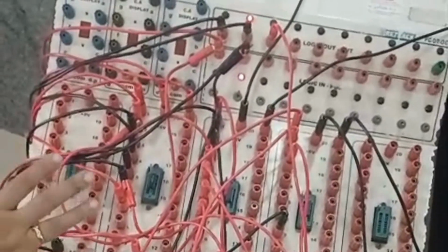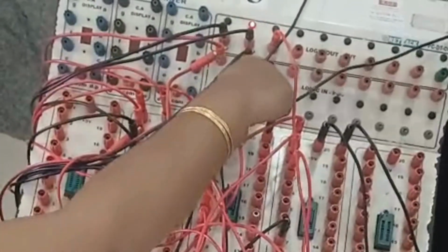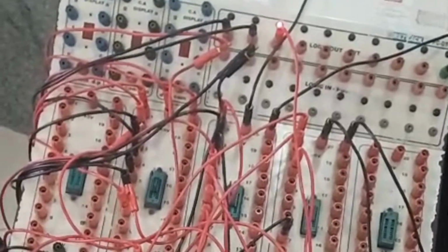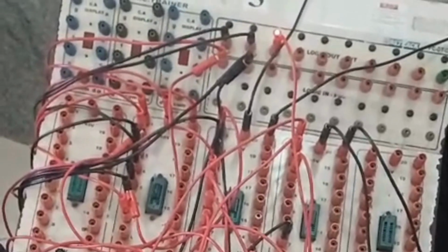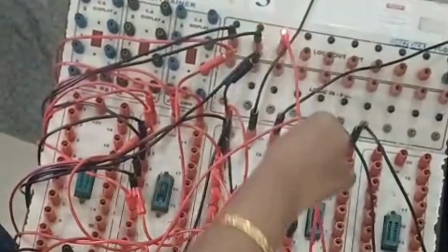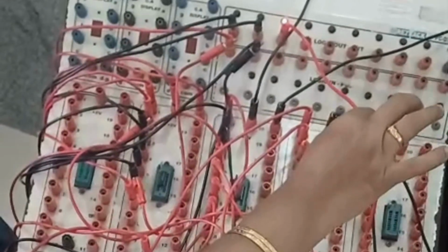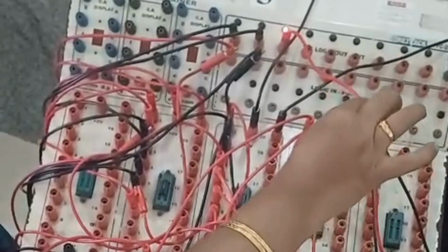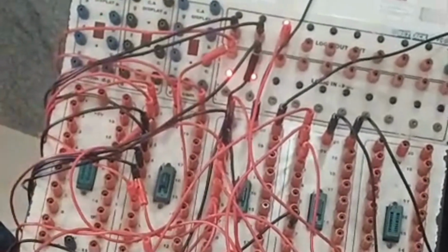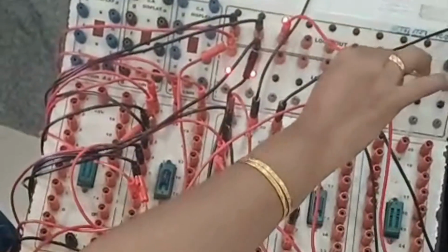Now let us verify the truthfulness of this circuit with the help of the truth table. According to the truth table, for the combination of A and B as 0, 0, A is equal to 0, B is equal to 0, so the comparison is going to say that these 2 bits are equal. This is the equal output variable, and this output is showing high value. So when both A and B are 0, 0, this output is glowing. Similarly, the same situation occurs when A is equal to 1, B is equal to 1. The output variable A is equal to B is glowing, which is high.